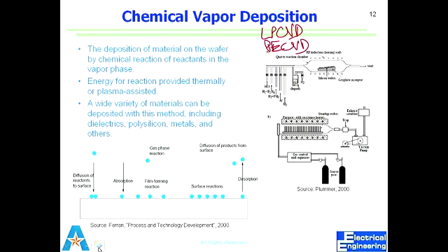And what happens when power reflects back? Damages? Yes, when it gets back to your power supply, it's going to fry your power supply, damage your power supply. And before it happens, you're going to have standing waves generated, which will be radiated if the wire is too long. It's going to act as an antenna, right?